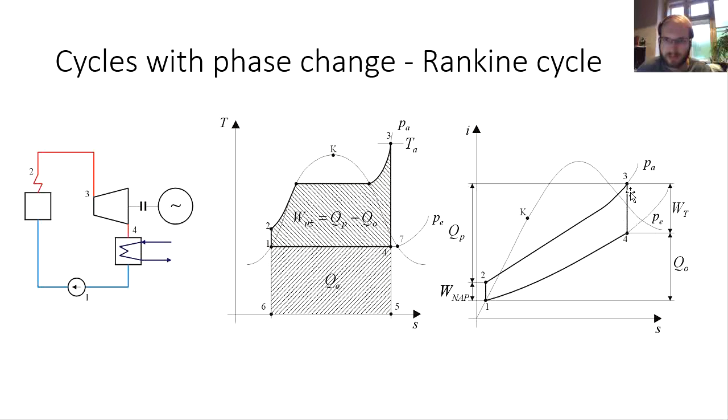Since work of the pumps or turbines is just the difference in enthalpy, once we get the enthalpy values, we can clearly get the work. And also during the isobaric processes, the heat exchanged is again the change in the enthalpies. So change in enthalpy between 3 and 2, for example, would be the heat addition. Change in enthalpy 4 to 1 would be the heat rejection.